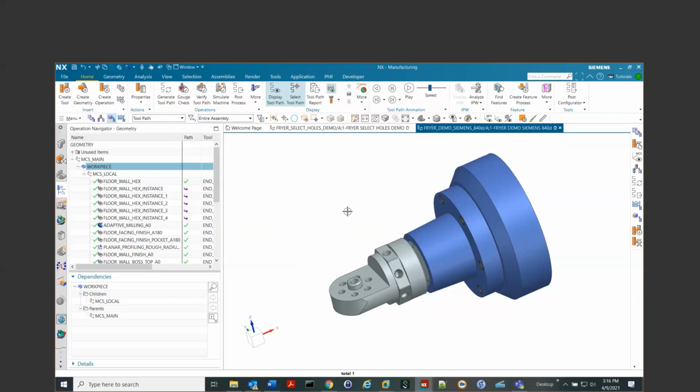And from there, I would guess that any place would want to compare the two programs and see what the changes were, and then change the CAM program to match what the edited program was, so you could always reproduce a good program out of the CAM system. In my world where I came from, the CAM system was the final word. If there were edits made on the shop floor, they had to be reproduced in the CAM system and a new tape file generated. Yeah, and I would say that's a pretty common practice.